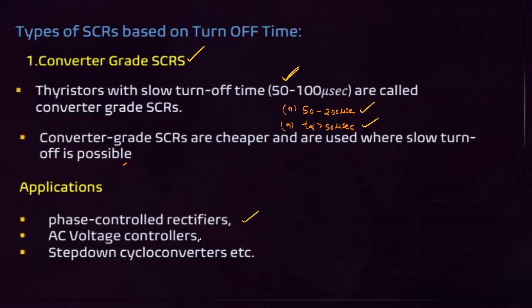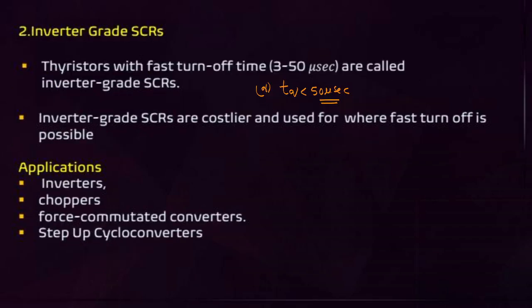Phase control rectifiers, AC voltage controllers, step down cycloconverters. They are using this converter grade SCR. That is the converters which are used for low frequency applications. In those applications only we can use the converter grade SCR.